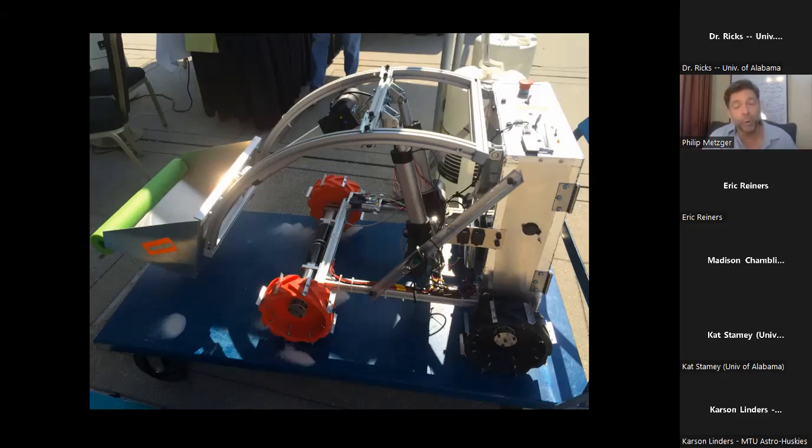Well, now the torque on the wheels should be the same on every wheel, but the strength of the soil under every wheel is not the same, because the soil is very random. And so one of those wheels is sitting on top of soil that's weaker than the other three wheels. It's inevitable, okay? So as you're increasing the motor torque, inevitably one wheel is going to be able to turn before the other three wheels start to turn.